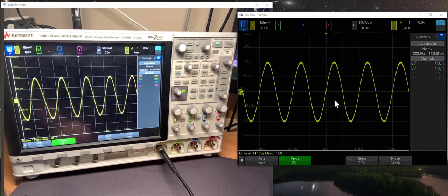The second important parameter is the period, and look, I can read that right off the front screen. Here's the 0 crossing, here's another one, this is 1 period. And see, that's 2 divisions. I've got the values for those parameters. Okay, now the scope is set up. I can read the important features of the waveform that I care about right from the front screen.